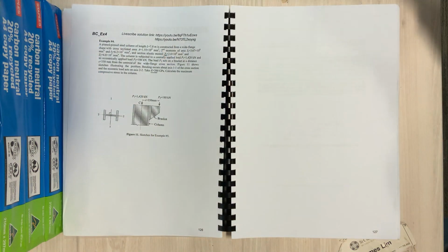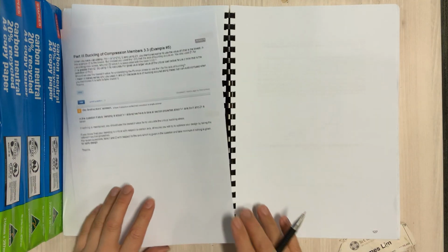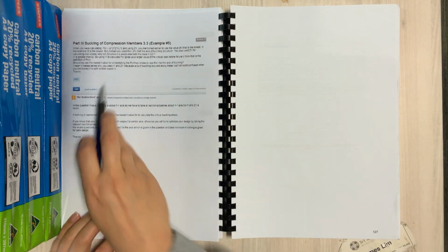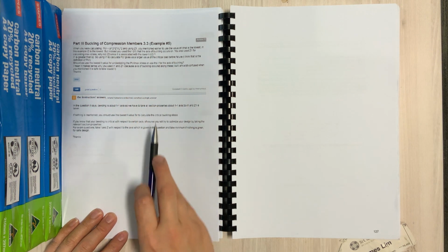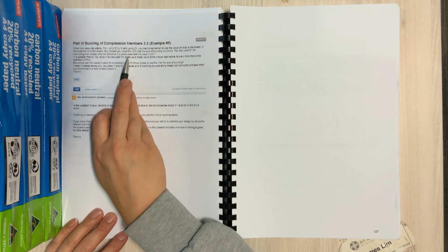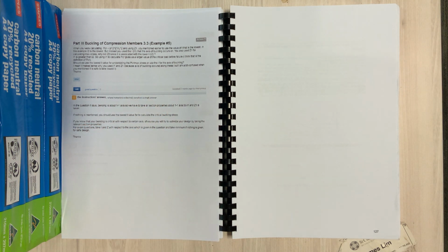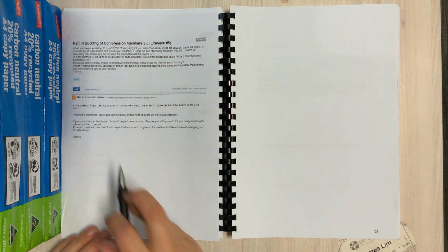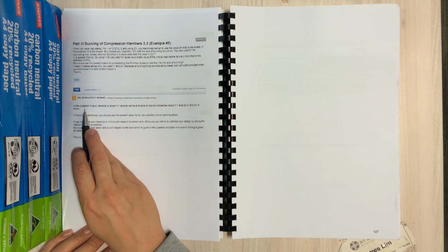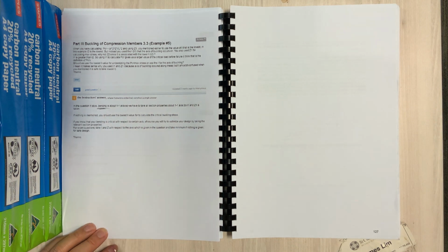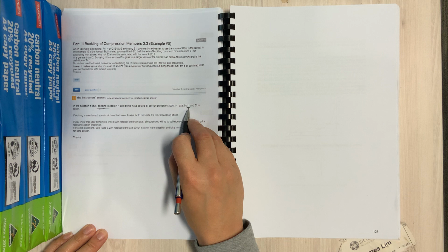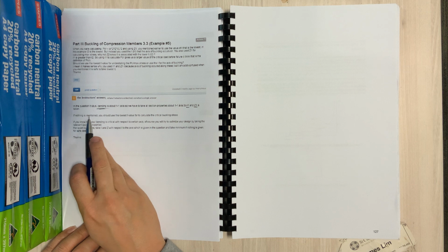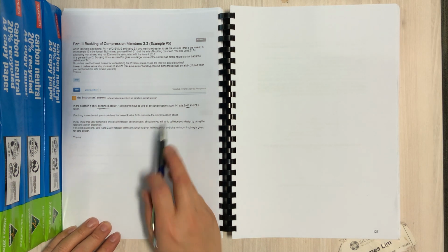So there were some questions about this one in previous years. If you get the file from the Dropbox, I've extracted some of the questions. This question is basically about the axis, because the red herring that I talked about, whether you use I1 or I2. I've answered the question by saying in the question it states that bending is about the 1-1 axis, so you're using the I1 and the I2. Then I've also made a note, if nothing is mentioned, you should use the lowest value to calculate the critical stress.